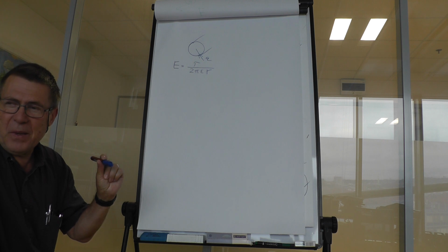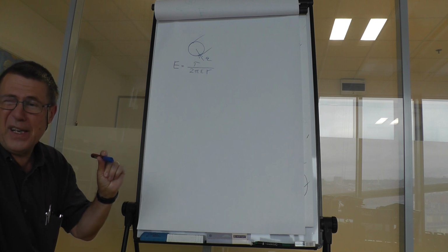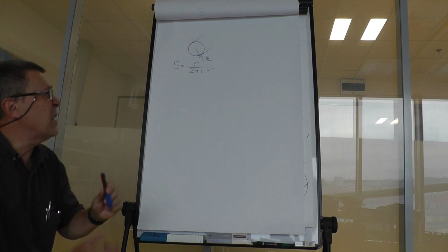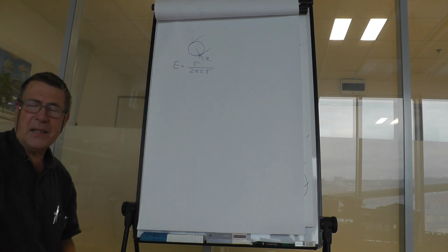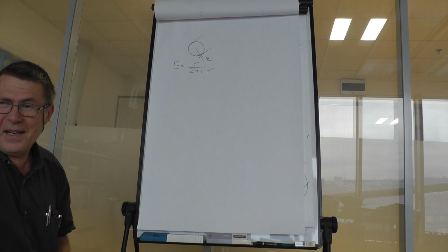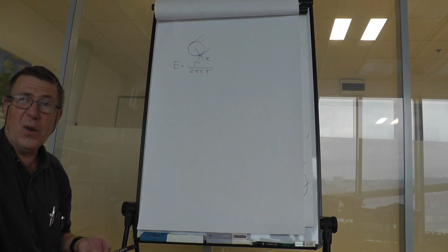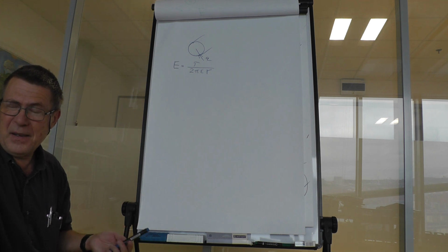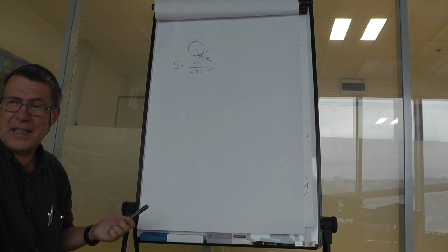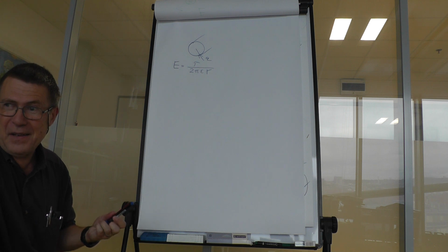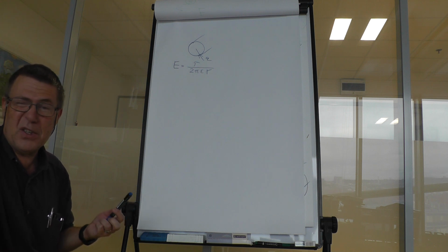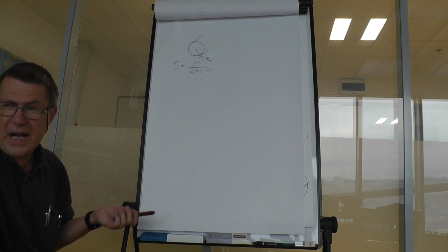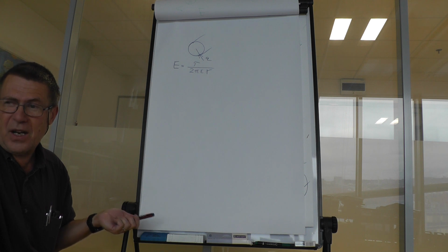We would be able to get rid of it if we increased the diameter of the wire, because then the electric field strength is decreased, and once it falls under the maximum strength which the air is capable of bearing without destruction, without discharge, there is no more any silent discharge.